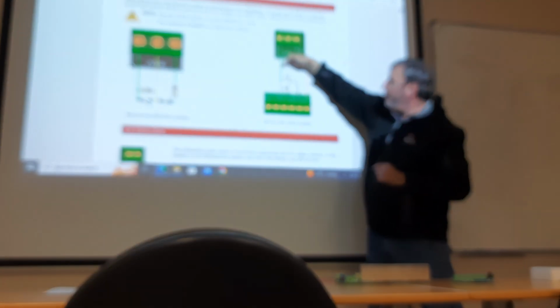And let's say I want to connect to zone 1, I'm going to take that zone wire to common, and I'm going to take those 2 resistors, put both legs into the other tamper connection, take the one to normally closed and the other one to common as well. Then it will pick up if somebody opens the device, if your unit has got an anti-tamper switch in it.